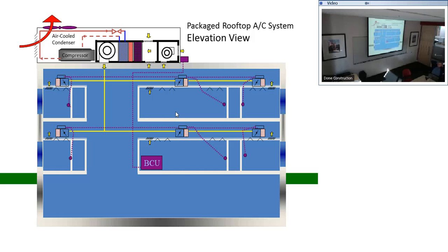How does the variable frequency drive know to slow the fan? It's the pressure sensor I put in. So I have an inch of water, let's say, and once these boxes start throttling back, that fan doesn't know anything, so he can't move as much air, he's on a curve, and he just starts building more pressure.